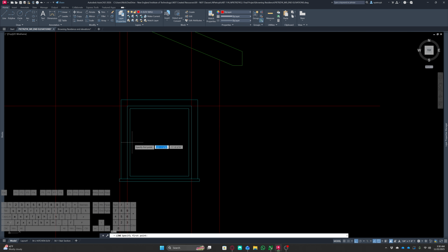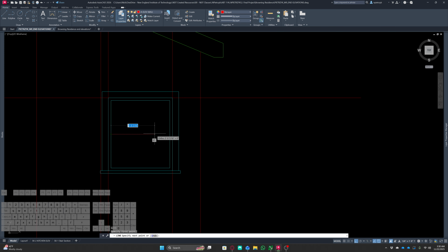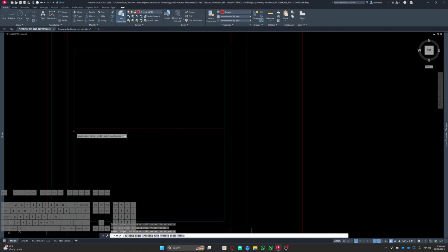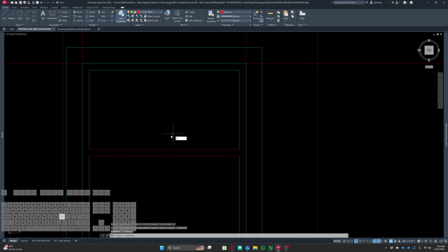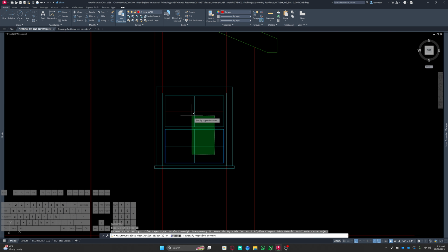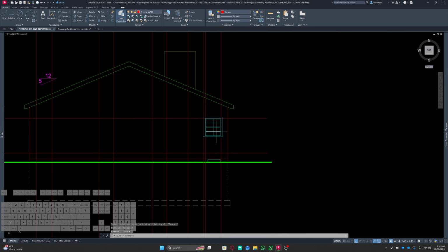All I need to do is grab a line down the center, or rather I'm going to make this current. I'll do it in a second. I'm going to draw a line down the center, offset by 1.5 inches, straight up, trim, line, and line. Finally, grab match properties and just make sure that this is all on the proper layer.